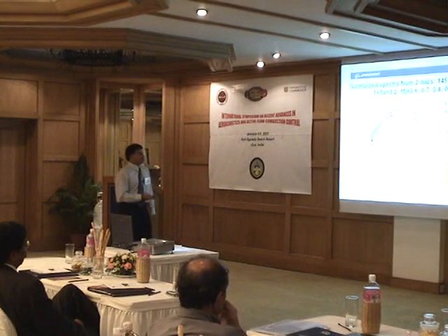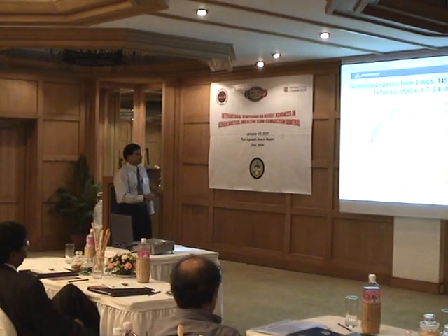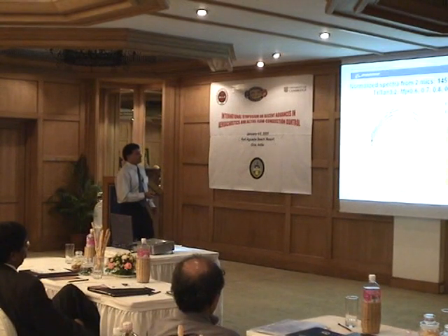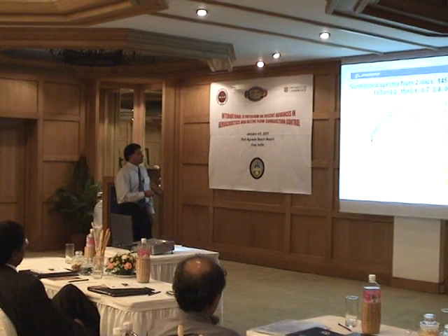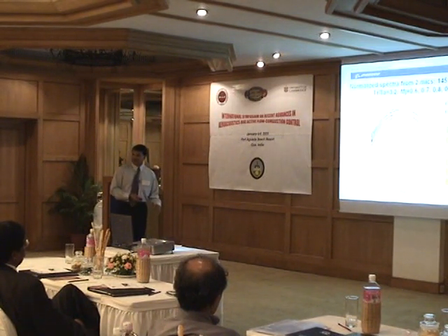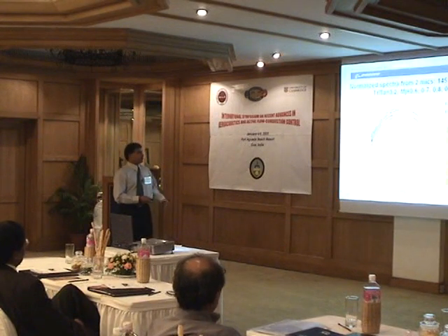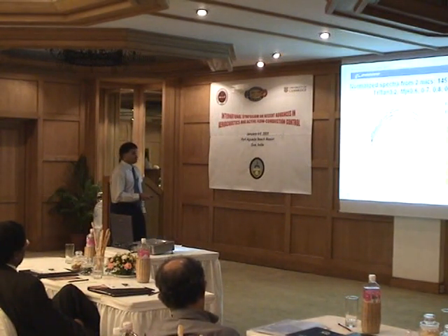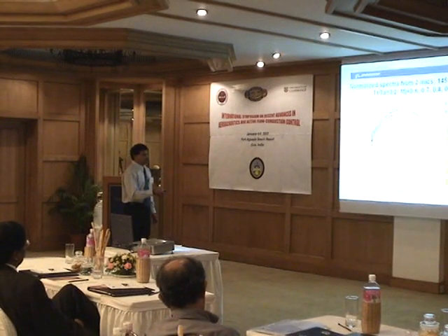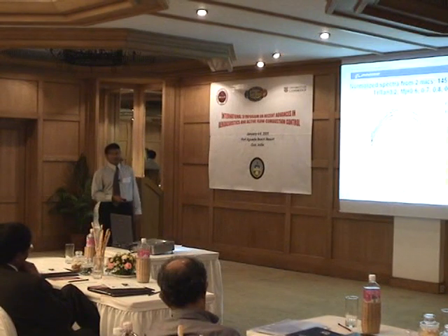So again, we do a collapse using 1 over r squared spherical spreading. And at the lower Mach numbers of 0.6, 0.7, 0.8, you get excellent collapse within a dB or so at the highest frequencies. But when you go to Mach number of 0.9 and 1.0, there's obviously a distinct difference in the two spectra, where you see the amplitudes being higher at the farther microphone. Again, if you have listed the convective Mach number and above a value of 0.8, it becomes slightly supersonic.